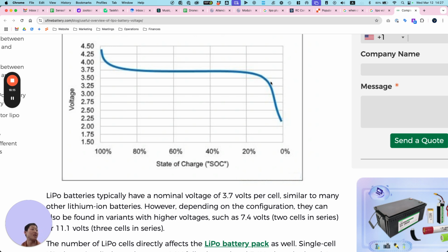We already lost 2 or 3 batteries from the drones last year, just from the FPV kits, because people let it sit plugged into the drone. And these are not DJI batteries. They're not smart. They're going to just keep pulling from the battery. The battery's not going to shut itself off. So it's very important that we be monitoring these batteries while we're using them.